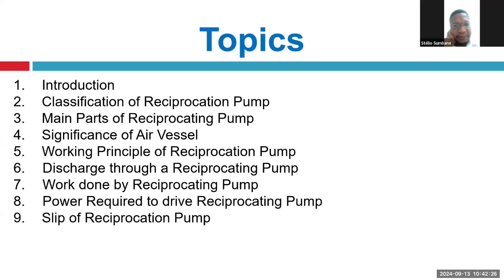In stimulation services, I have seen pumps delivering close to 5 cubic meters per minute. Essentially, these pumps do not deliver a lot of flow rate, so we daisy chain these pumps, with multiple pumps connected with each other. But for a single pump, 2 to 3 cubic meters per minute is quite common.